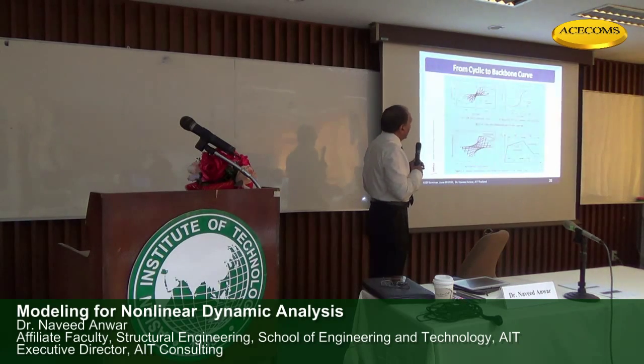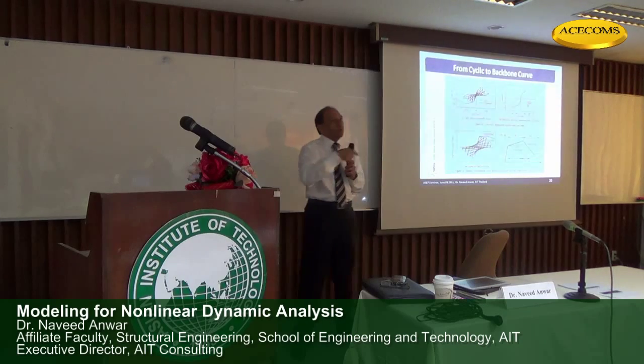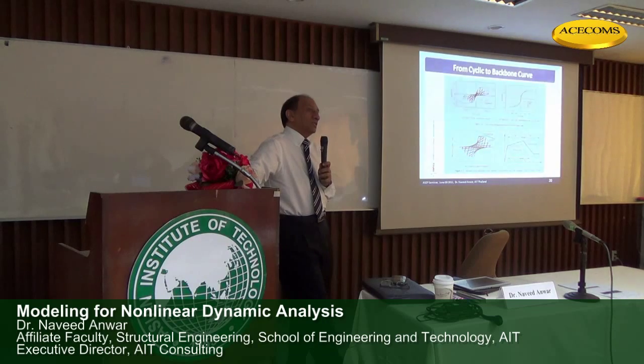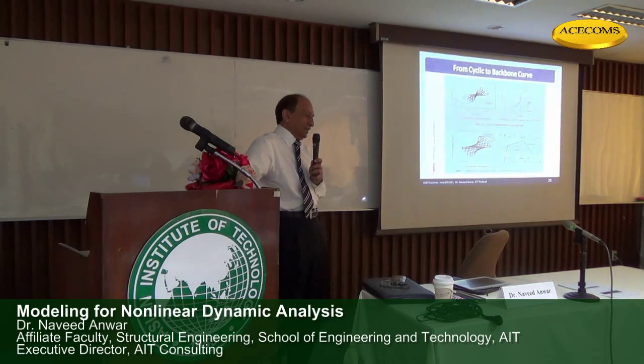So this problem with the backbone curve or with the proper static loop is one of the key problems at this time that we are facing in terms of nonlinear analysis accuracy, because this is not that accurate yet, and we have to rely on whatever best estimates we have.